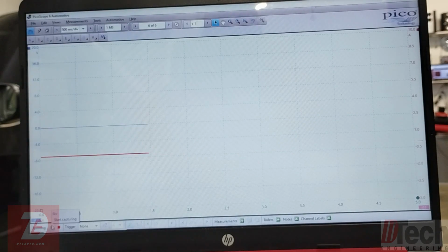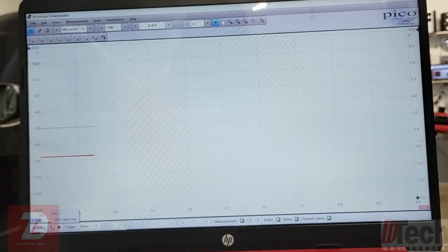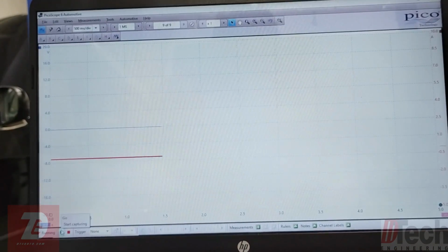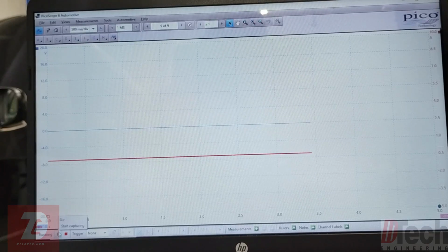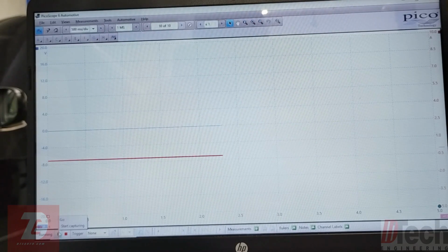Alright, so you saw me connect to the vehicle, clear the codes, start it up, recheck, no codes. Naturally, just out of curiosity, I've got the scope set up after the wire repair, and just wanted to see what it was going to look like with the same measurements, voltage and amperage.